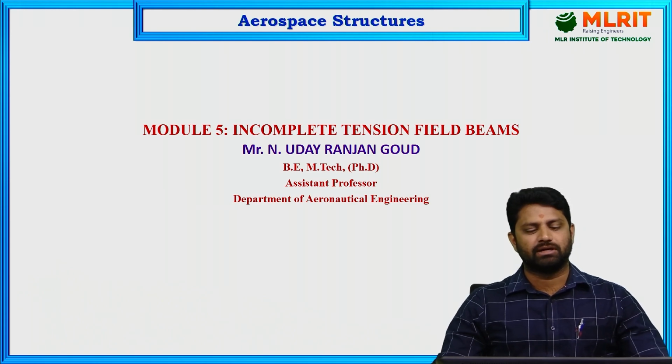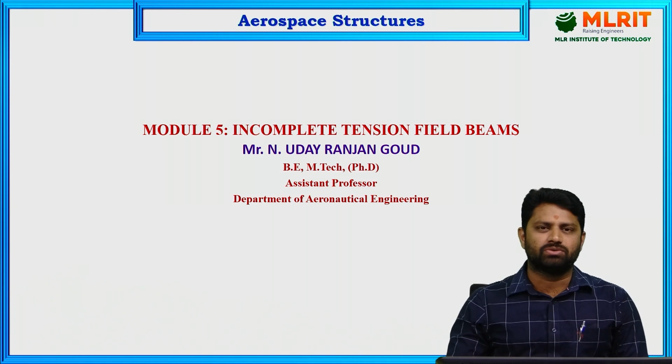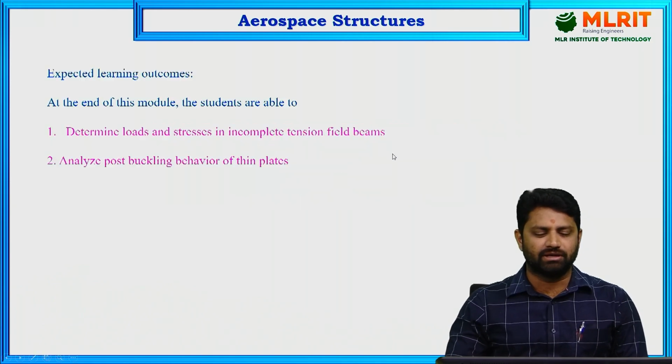Now when it comes to incomplete tension field beams, whenever the loads are applied, even near failure, the plates retain some capacity to hold, so they will be in a state of tension as well as compression. Therefore it is very important to study incomplete tension field beams.